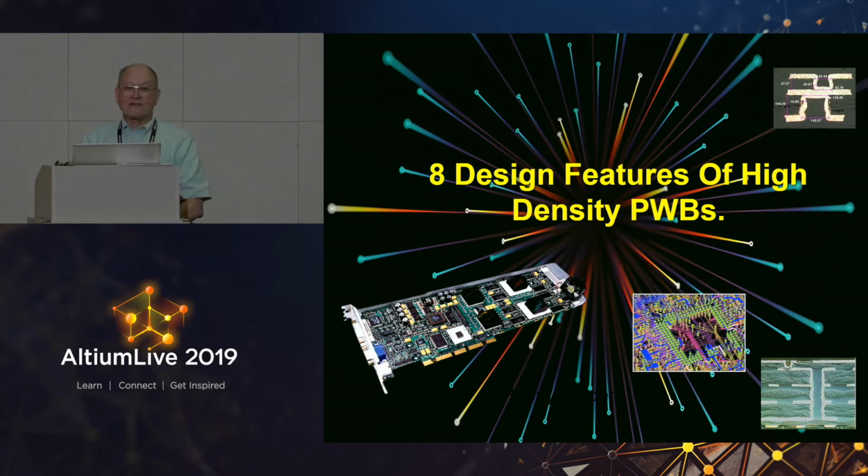Anybody here with an RF background understand coplanar waveguide power distribution? Well, if you're an RF guy, you say, oh, that's not new. We've been doing that in RF radio since World War II. Yes, I agree, you have. But in the digital field, we've never done it. We've always used planes. And you don't need power planes. So if you can understand that you don't need power planes, how many other things are you doing that you don't need to do because we've always done it that way?